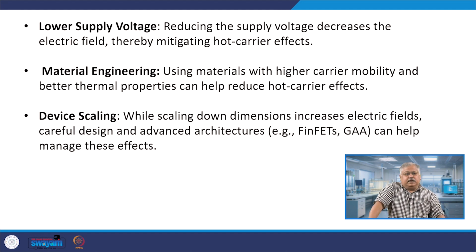And especially the latency. But if you lower the supply voltage, again the idea is to reduce the electric field. If you are able to reduce the electric field, you can do many other things with that, but this is not, I should say, a gallant way or a good way of doing the job. The better solution is the first one, the LDD, and the other two which are presented now, the material engineering which we do.